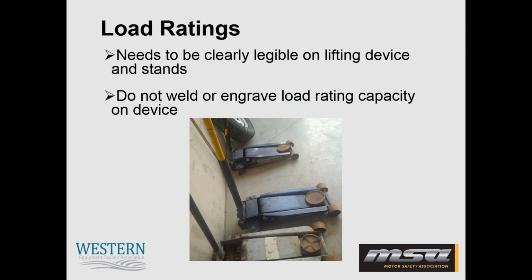I'm going to talk now a little bit about load ratings. Your load ratings need to be clearly legible on your lifting devices and stands. This needs to occur at all times. And again, I snapped this picture at one of our facilities that I inspected, and these floor jacks were not labeled. I also saw in one facility where they welded and tried to engrave their load rating capacity on the device. And you're not supposed to do that either, because it affects the structural integrity of your jacks if you are engraving or welding into them.